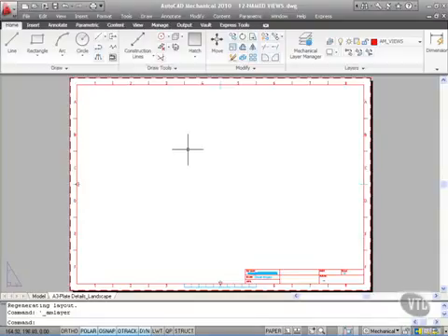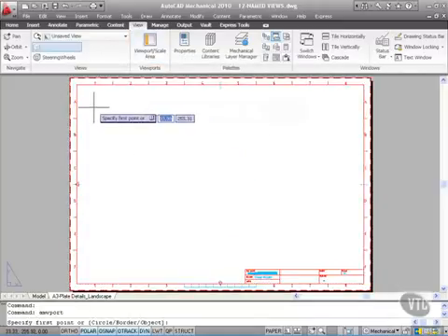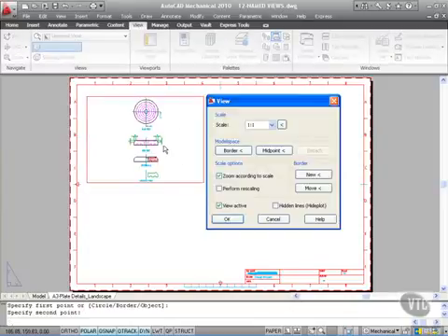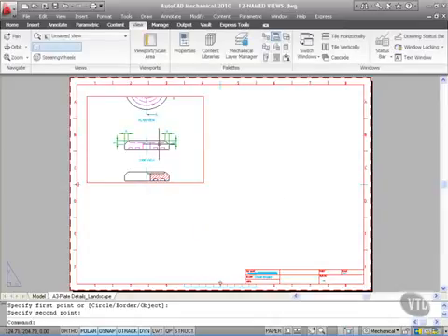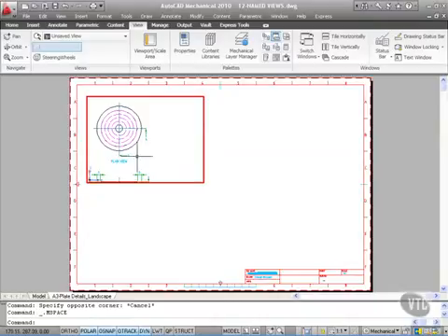OK. So what I've got to do here now is generate some viewports. So I go to the View tab on the ribbon again, Viewport Scale Area. So this time when I click, unlike scale areas, I'm just going to click, drag my window like so, and it will show me everything in there. Now, do I want the scale to be 1:1? So I can now set the scale of my viewport here very, very quickly and very, very easily. Yes, I do want it 1:1. So I'm just going to click on OK, and that scales it at exactly 1:1. I then double click inside the viewport, hold down the wheel on my mouse and pan. I don't want to zoom. So I get that where I want it, my plan view.